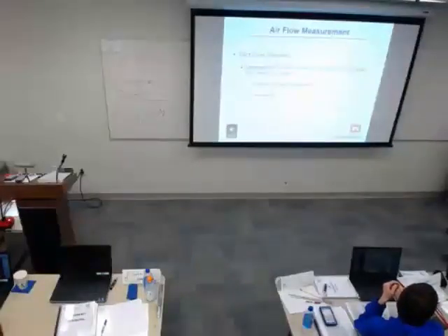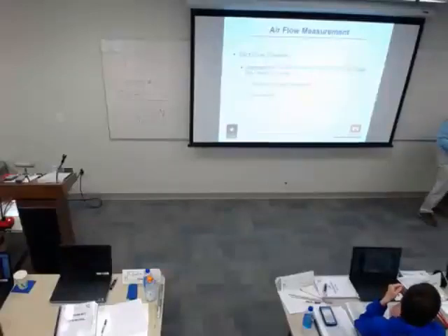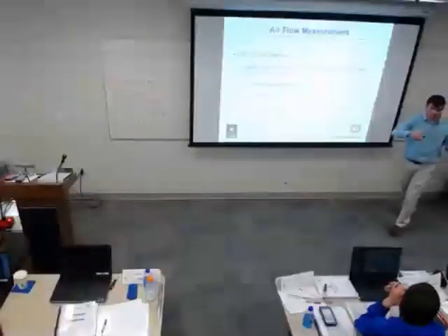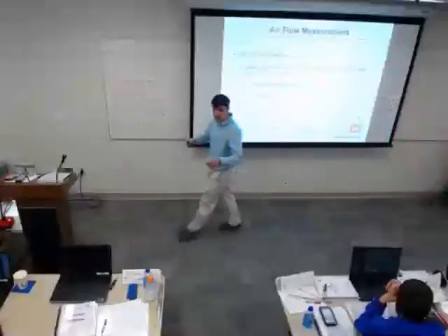Yeah, you can actually detach this piece from it and hook it up to either a pitot tube or a grid that'll let you not have to take quite as many measurements across the coil or something like that, and give you a better average.